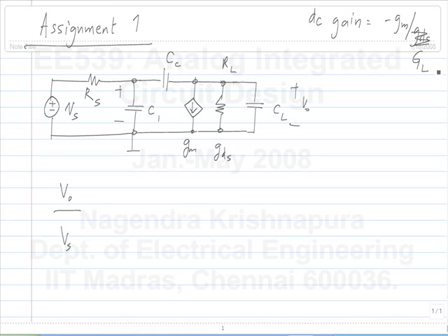But is that familiar to everyone, the concept of independent state variables? What is the order you can have with 3 capacitors? Maximum of 3. Okay. So, you can definitely say that it's not 4th order. But beyond that, you have to do a bit more analysis. Does the order have to be anything? Can you have 0th order with 3 capacitors? Or can it be 0th order, 1st order, 2nd order? Okay, let's say that we do not do something so nasty to the capacitor. It can be 1st order.